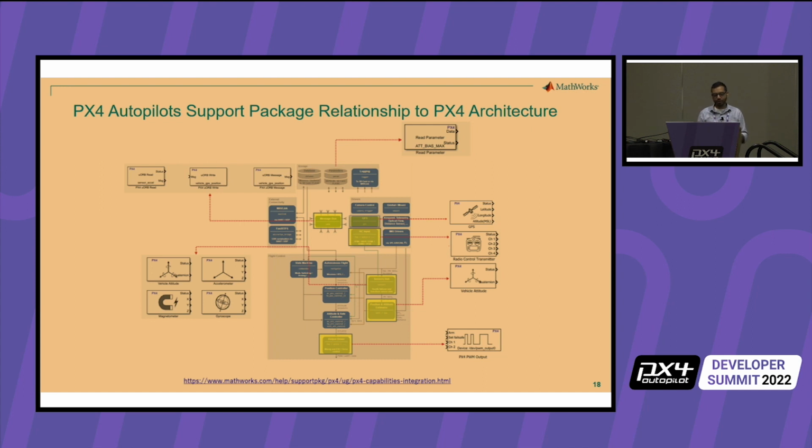When we talk about deploying to the Pixhawk, what we do is disable both the position controller and the attitude and rate controllers, and we deploy our own app. I'm not sure if you're familiar with how you can push a custom app to the PX4 firmware.